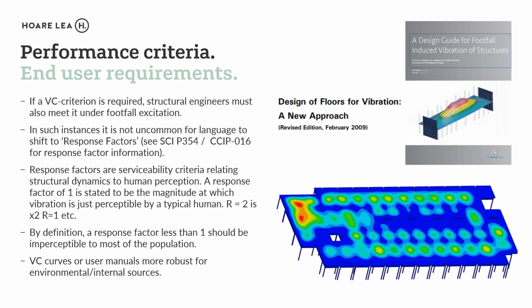And response factors are actually based on acceleration that's weighted to human perception of vibration, in a similar way that we would weight noise levels to better replicate the perception of human hearing. A response factor is a dimensionless score, if you like, so there's no units assigned to it, but a response factor of 1 would say just about perceptible to most of the human population. A response factor of 2 will be twice the amplitude of vibration of response factor 1.